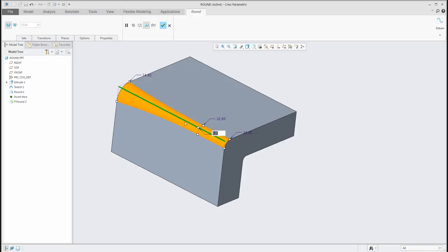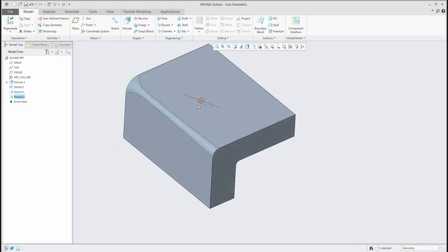So if you would like to be in the middle of the curve, you can select the number 0.5 and the selected radius will be directly in the middle. Or you can specify a different radius manually, or you can select and drag, no problem. And you can change, for example, 20% of the end or another side. It means 80%. Yeah, 0.8. And if you finish, the system will create a variable round for you.